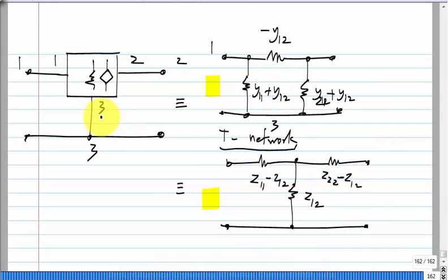This makes the y parameters not symmetric. Y12 is not necessarily Y21 and Z12 is not necessarily Z21 and so on. Now, we already know the circuit representation of some such network. You have 2 resistors and 2 control sources. But what I am trying to do is, can we tweak this network just slightly so that it will represent the general 2 port network?